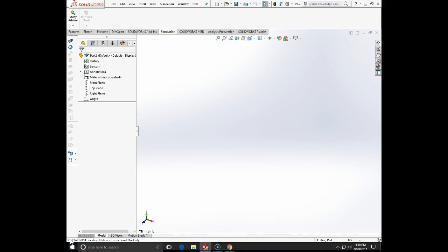Finally, we will verify that a clearance exists by using the Evaluate tab and clearance verification. And the clearance will be shown there, and we can actually specify the amount of the clearance. So let's start by making the two parts as per our figure 560. Going to start making the block base, and then I'm going to make the block top or the block ring.